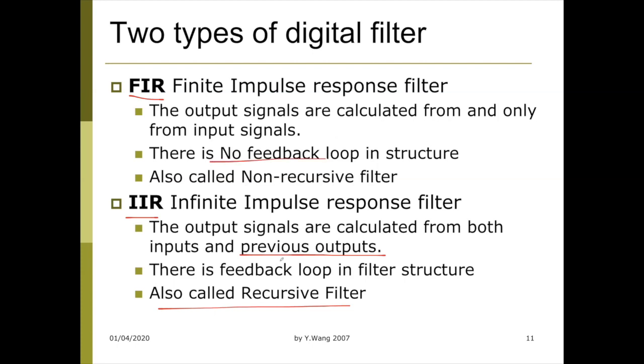Whereas with IIR, it can happen. If you don't design it properly, you'll end up amplifying certain frequencies up to the maximum and clipping. That's an unstable design of an IIR filter, which we want to avoid. But the advantage of the IIR filter is that it normally takes a less complicated structure to implement a certain filter because it can use output information. In practice, we will see more.